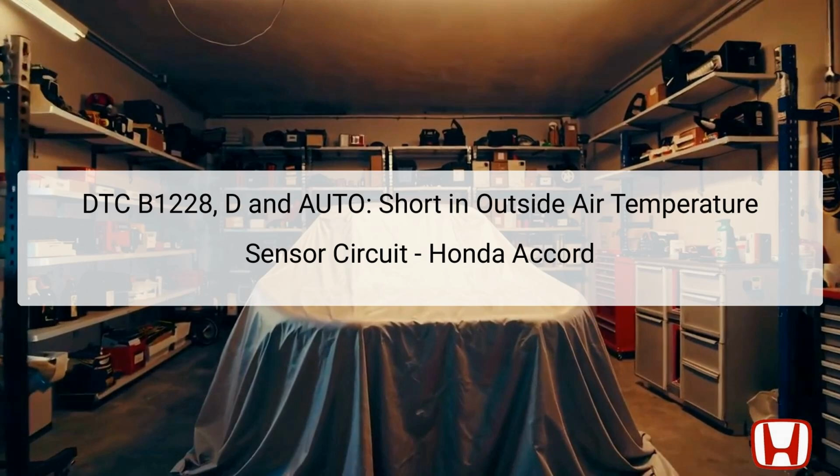This sensor is usually located in the front grille area or near the radiator, providing real-time data to the climate control unit, which adjusts the air conditioning or heating accordingly. When there's a short circuit in this sensor circuit, the climate control unit may receive inaccurate readings, leading to potential climate control malfunctions, affecting both user comfort and vehicle performance.